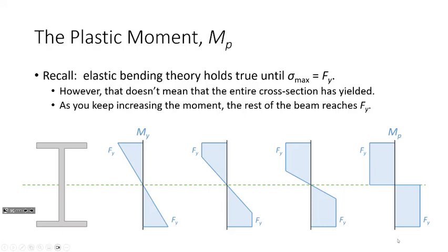So when you're designing, you would just accept the deformation at the extreme fibers? Yes. Yes, you do. In fact, if you actually look at the plastic zone around where the central section reaches Fy, you get that yielding all the way out. You didn't expect me to say that, did you?